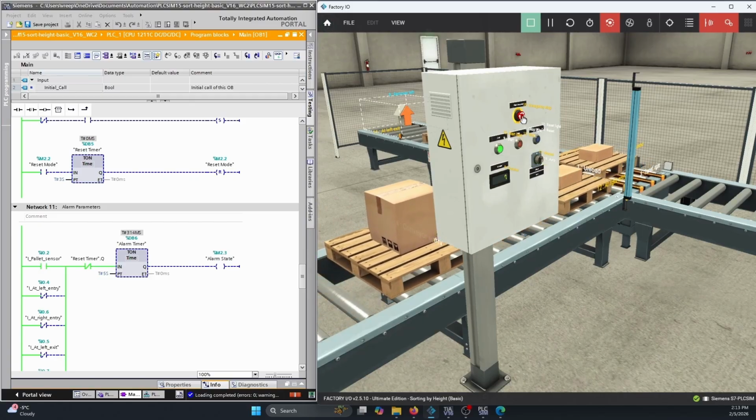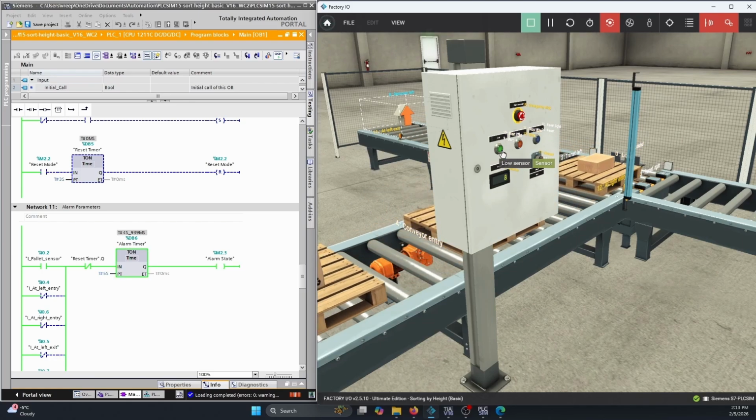And then if it were to stop here and block one of the light outputs, we're going to go into the alarm state. So once we reset the e-stop, we're going to have to reset. So tapping the reset, and after 3 seconds, 3, 2, 1, we have a solid red light. So now we can start the unit back up again, and everything's rocking and rolling. This one got blocked for a little bit more, so we've got to reset this one more time.